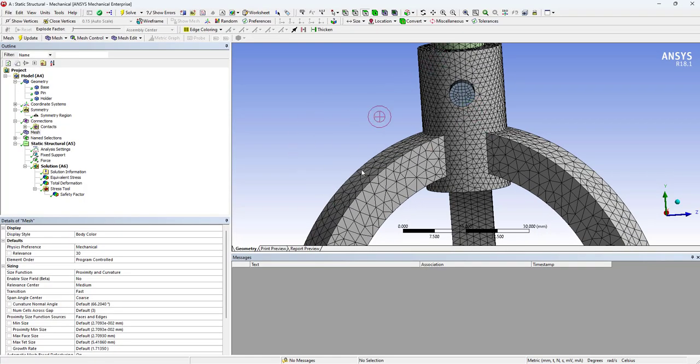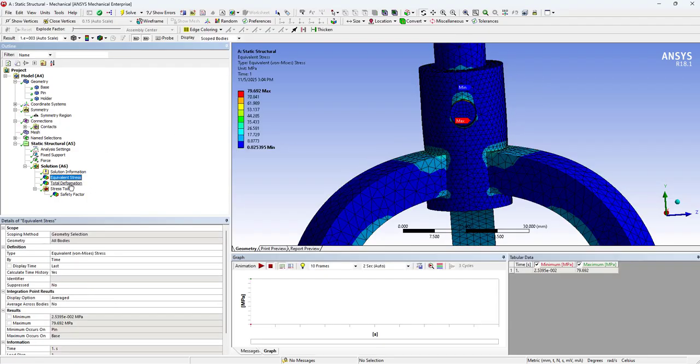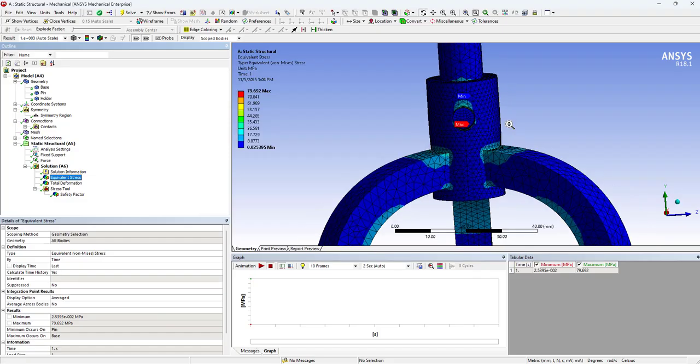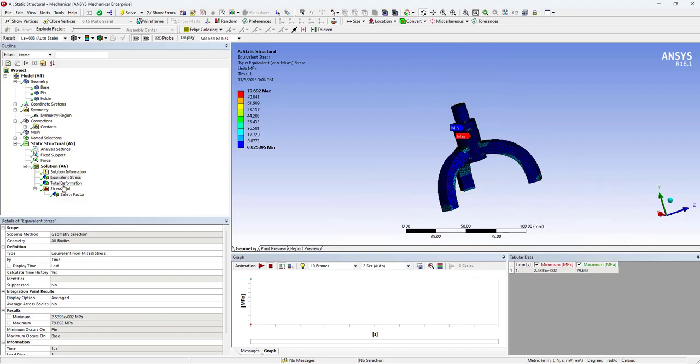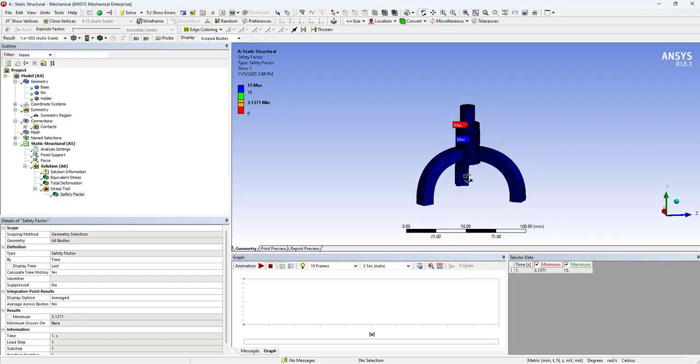So this left portion that is created, ANSYS will not solve the matrix for this. So this is just a graphical expansion of the results, without consuming any resources. We are viewing the full model here without reanalysis. So this is just a graphical expansion, and we can review the full model using this one. So this is how you can use the beta options for viewing the full geometry when you are using the symmetry option and model the assembly in ANSYS.